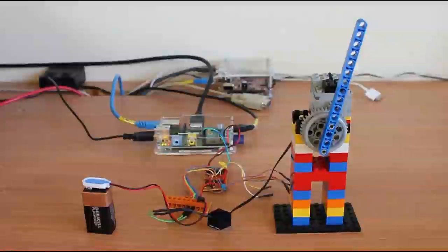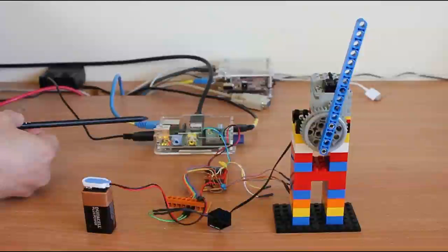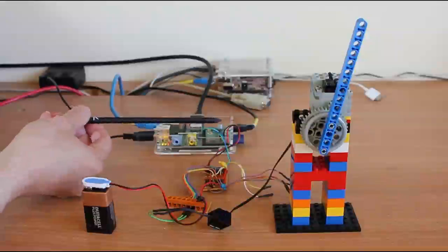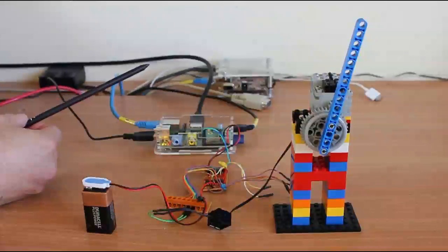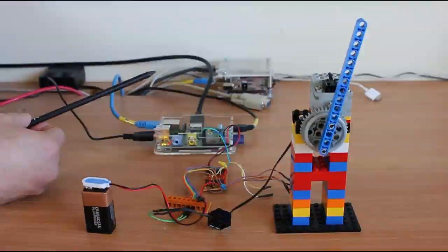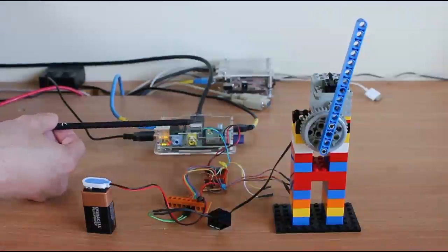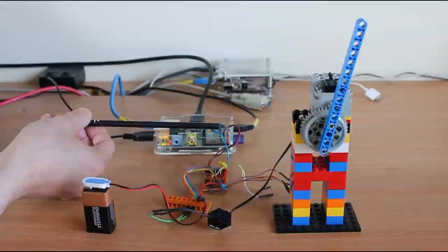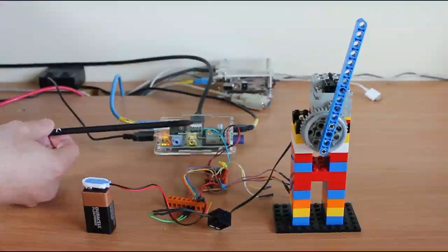Here we have the hardware setup that we're going to use for our demonstration. We have our Raspberry Pi, which is connected to the network so that we can access it through SSH. We've got an SD card, which is configured with the Raspbian distribution and has booted off that, and then we've got the Java ME Embedded 3.3 installed and running on there. What we've then done is to connect some of the GPIO pins that are available on the board. So we've got a plus 5 volt line, we've got ground, and then we've got pins 7 and 8 connected.